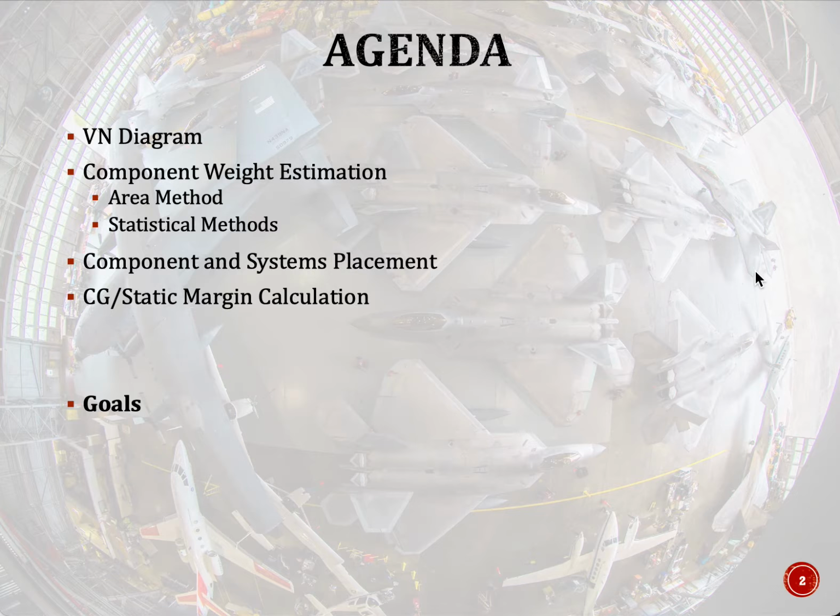So this will be one of the most involved processes that you go through in the air design, mainly because there are a lot of components on the aircraft and it's very important for us to estimate the weight of those components in a relatively accurate manner, right? Because if you think about it, the entire performance and the cost of the aircraft really depends on the weight itself, right? Yes, there is sophistication involved. There is technology advancement. Ultimately, it comes down to weight, right? How much weight you have ultimately depends on how much fuel you need to satisfy a certain mission, right? So that's why this is one of the most involved processes in the air design process.